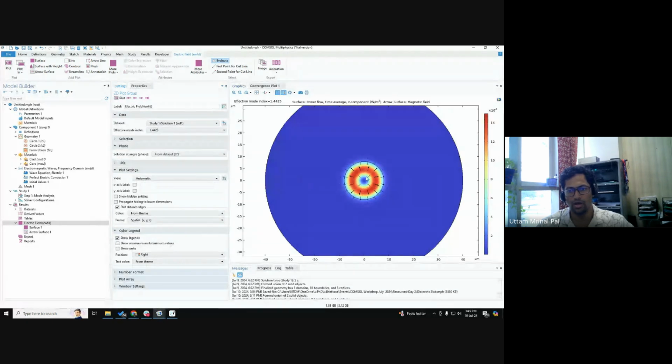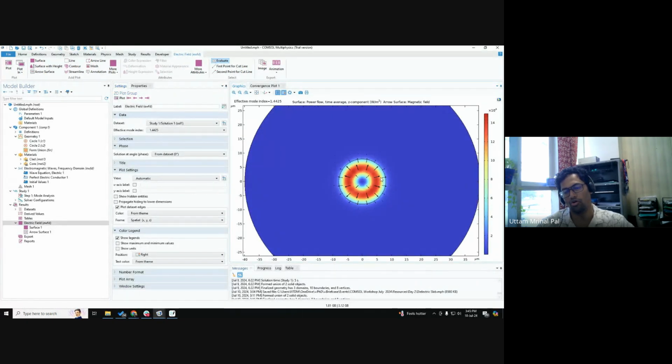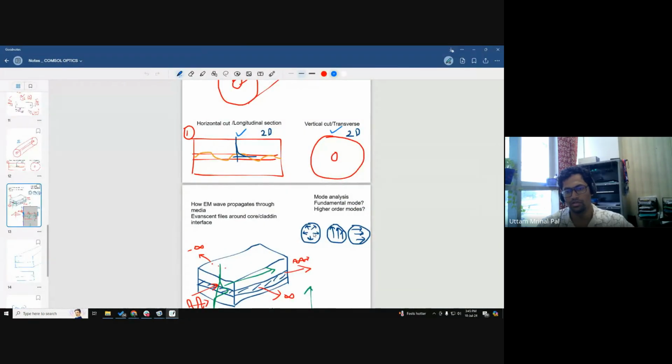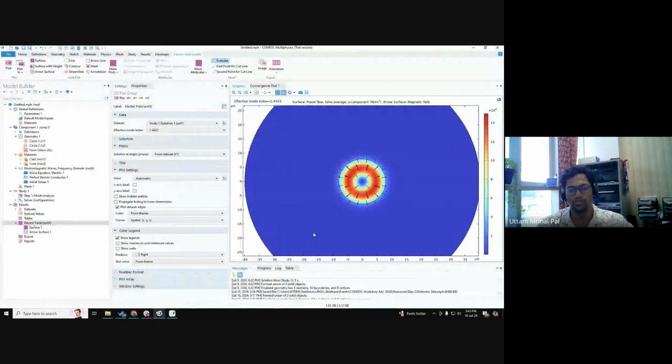And then you go for higher order modes. You see this mode, in which all the arrows, electric field or magnetic field, are perpendicular, so just complementary. It's coming outwards, right? So if I plot the electric field in this case, it will be circular. And then here is one more hybrid mode. There are all these other modes. These are all leaky, trivial modes. These are all non-trivial modes. So this is how you can actually visualize a specific mode.